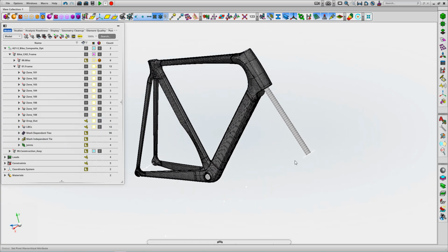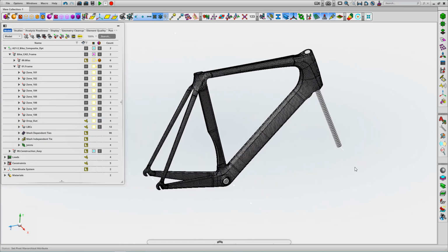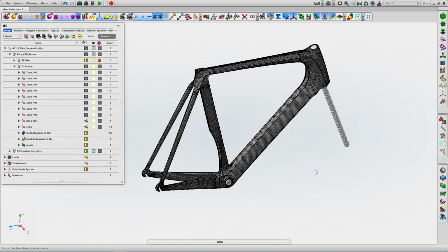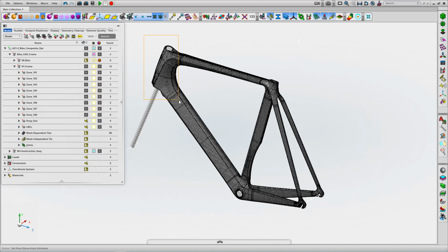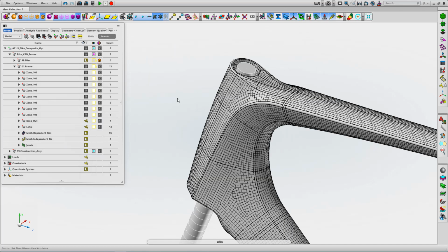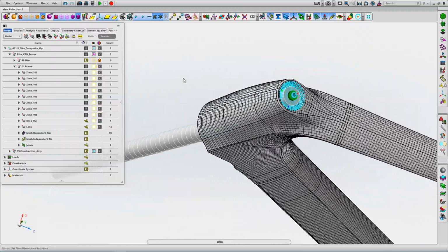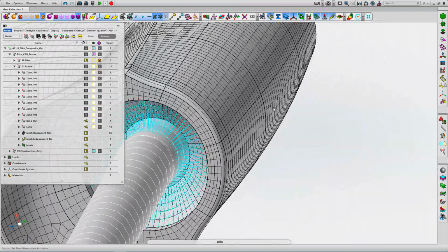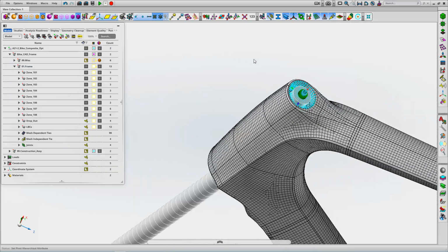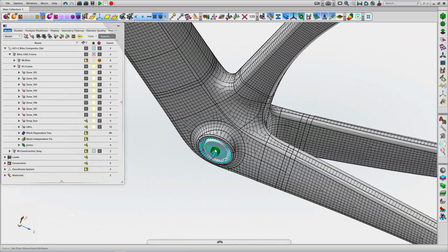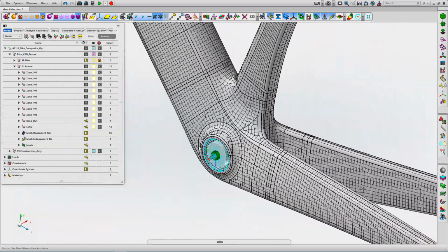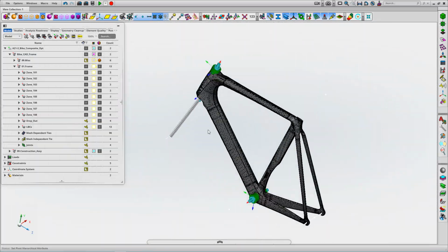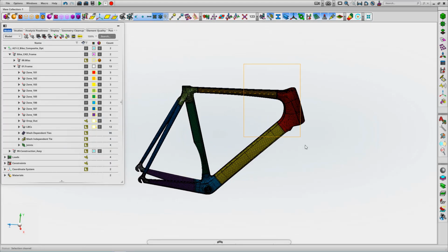We've got the fork idealized based on a sort of standard certification type loading, so maybe the ISO loading constraint. So we've got a rigid bar that represents the fork, and we've got some joint definitions that can be used to model or to idealize the bearing interfaces, so allowing moment transfer, or the appropriate moment transfer, at the head tube and at the bottom bracket interfaces as well.